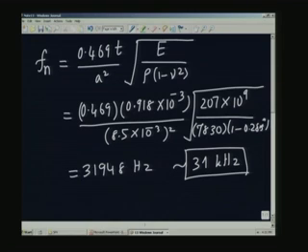In principle, if I am going to use a diaphragm gauge of this type, I can probably subject it to a transient which is probably half of this, or for example, up to 10 kilohertz or 20 kilohertz. There should be no problem in using this. So, the frequency at which it can be operated, if you are going to use it for measuring a time varying signal, is partly determined by the natural frequency of the gauge itself.